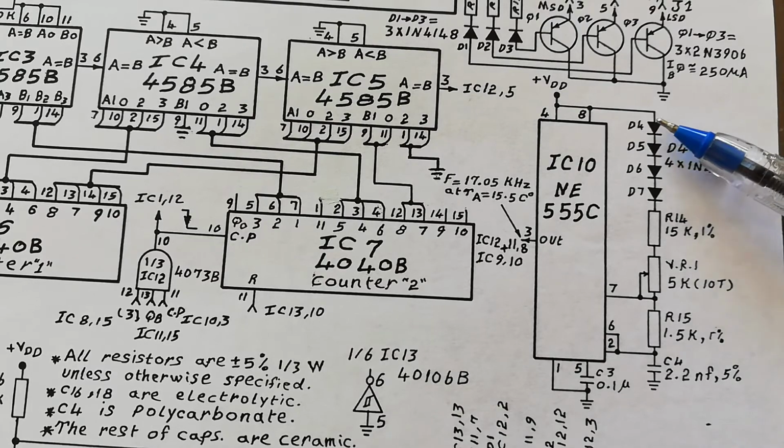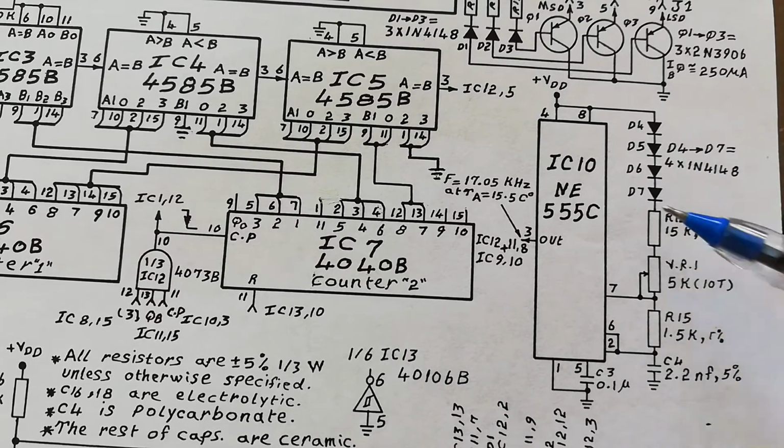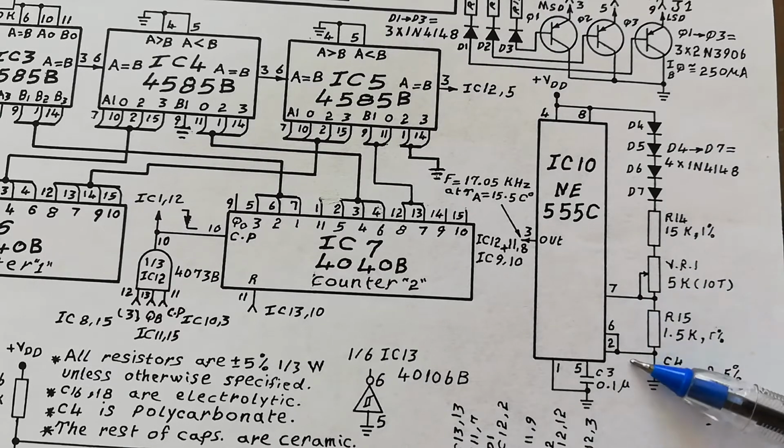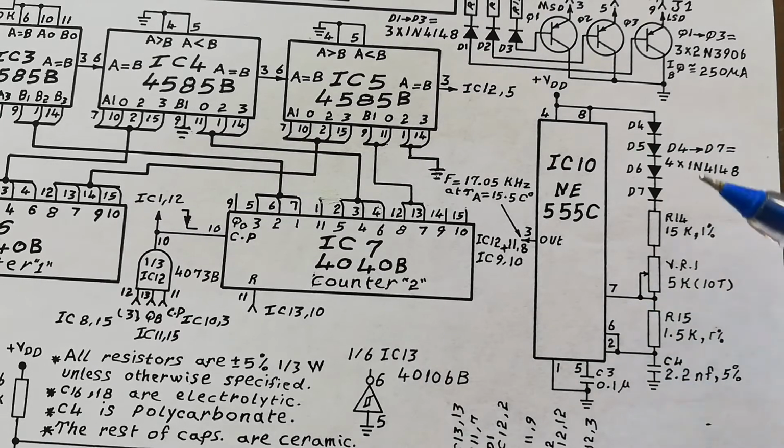So we are talking about relatively about 3 volts. So whatever the V plus is, you're going to deduct 3 volts here, and that, of course, will make it slower when it charges. The discharge is no problem, because that will be handled internally, but the charging will be slower.